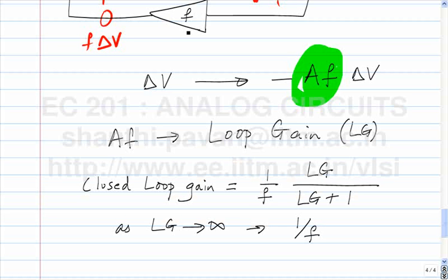And on an IC especially, if you make two identical resistors, even though the resistors may drift off from their absolute values, the ratio of resistors remains very, very stable. Even though R1 and R2 vary, R1 by R1 plus R2 can be very, very stable.